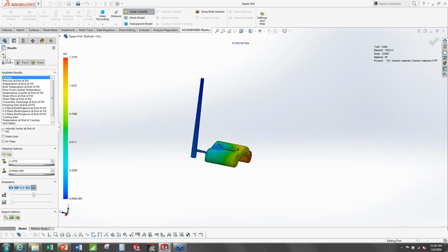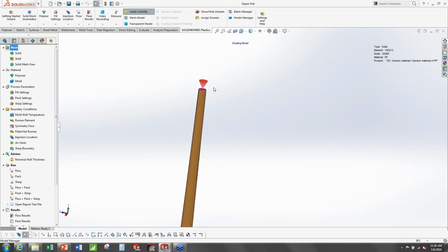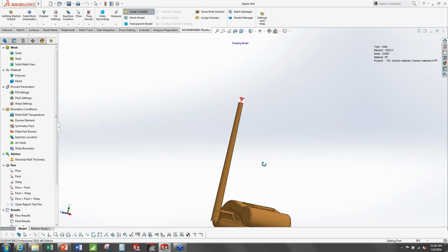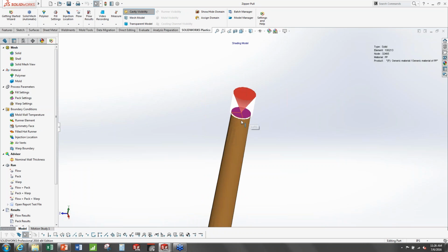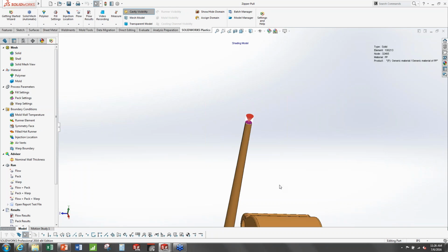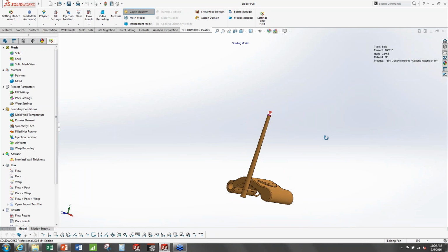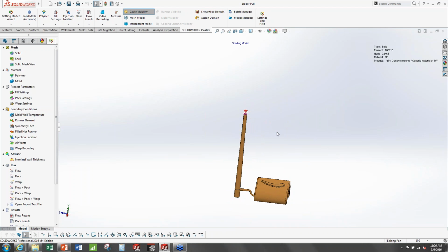One other thing that I wanted to show you was the gate location. Basically, when you do 3D modeling of a part in a runner system, you create that gate location at the end of the screw. Just like Shaun had showed you before with the split faces, same thing that you put on the end of the screw to create the gate location. Again, with SOLIDWORKS Plastics, you can change fill speed, pressures, and temperatures to simulate and do those iterations to be able to really understand what process parameters really affect the quality of the part. And at this point, I'll turn it back over to Shaun.